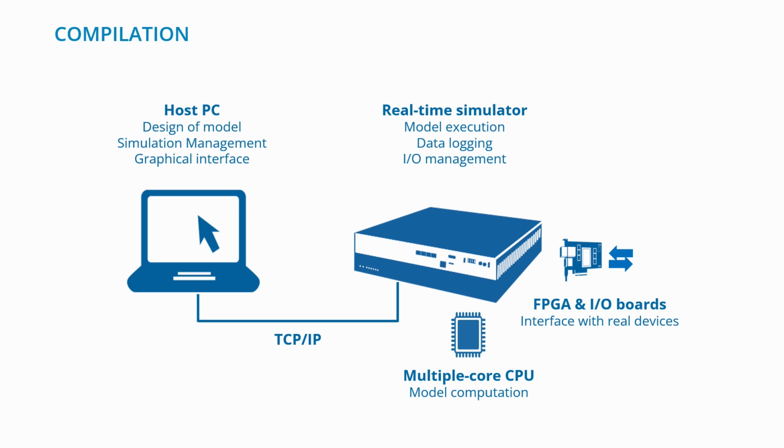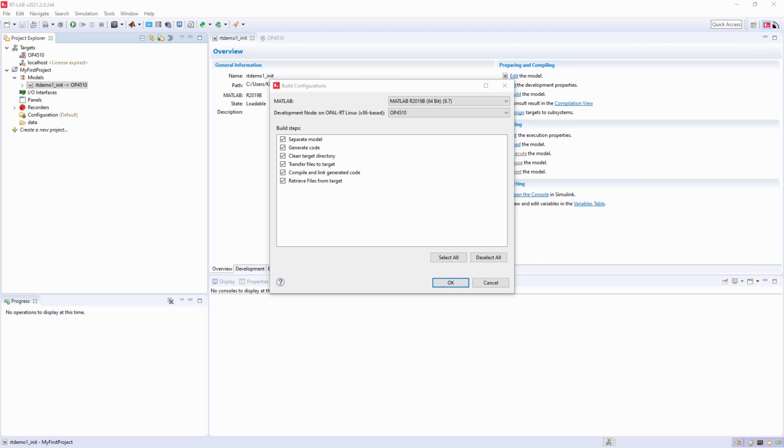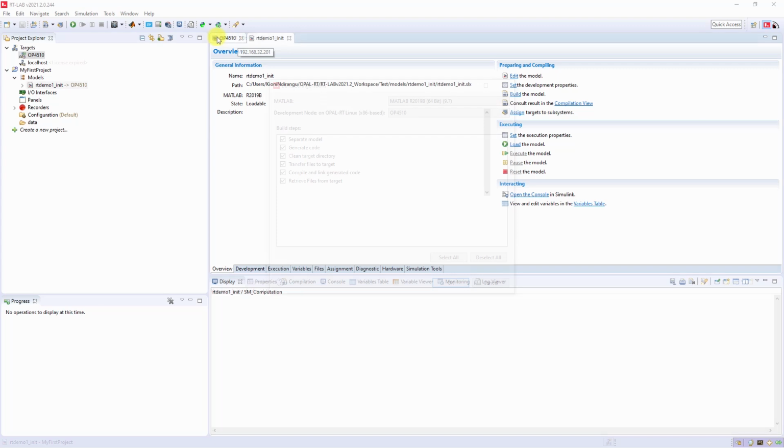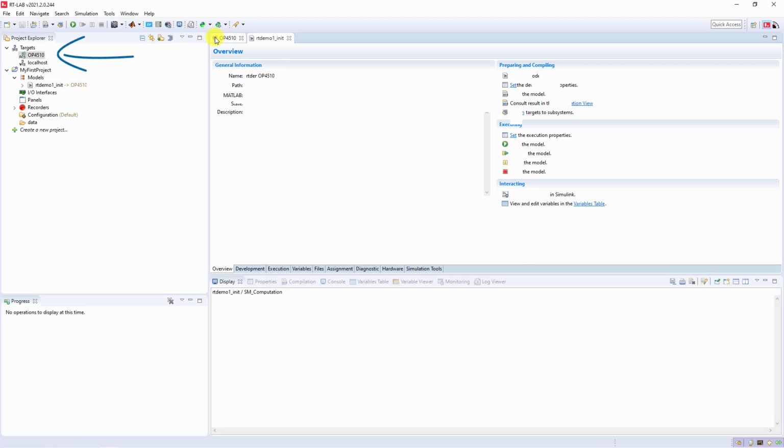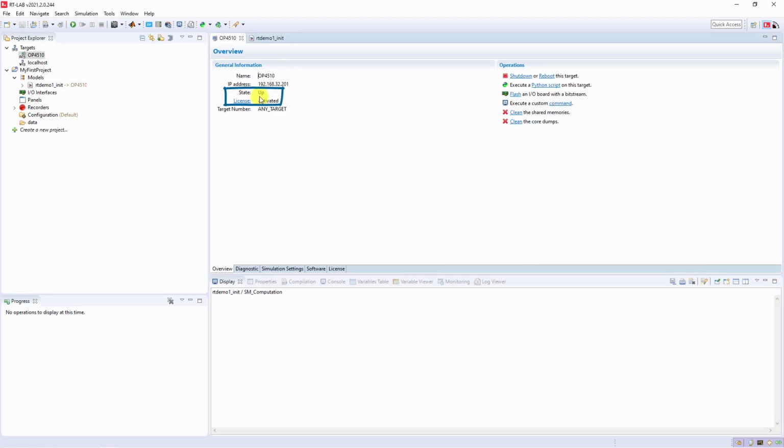Therefore, to take advantage of the user-friendliness of Simulink while also respecting real-time constraints, we must work with the two environments and be able to convert between them. This is done in two steps. First, the Simulink model is converted into C code by the Simulink coder. Second, the C code is converted into Linux executables by the computer on the target. Since step 2 occurs on the target, it is mandatory to have access to the target or a virtual machine to complete the compilation process.